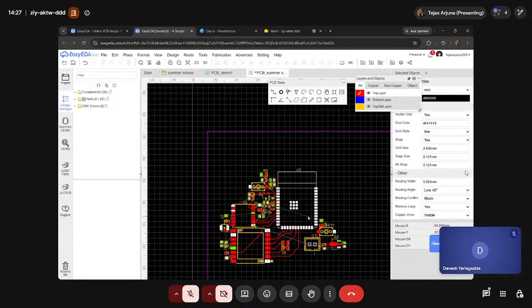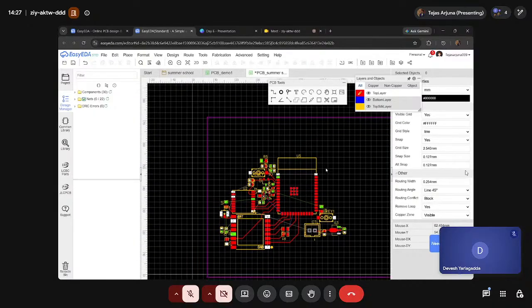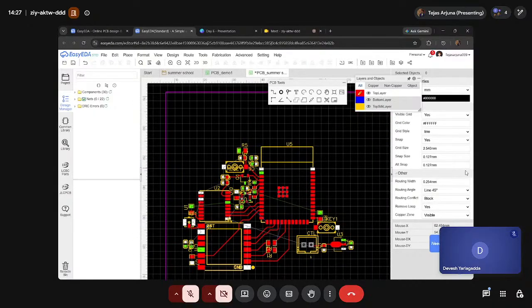So a loop is what? A loop is when it starts from the VDD itself, the VDD to the internal circuit to the ground and goes to the ground of the ESP32 and goes to the ground of the regulator or the power supply. So this is a big loop only. So how do we reduce that? We don't connect the ground again through traces to the ground here. That will increase the loop area.